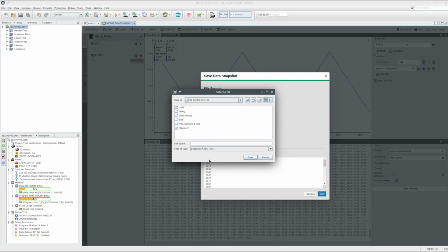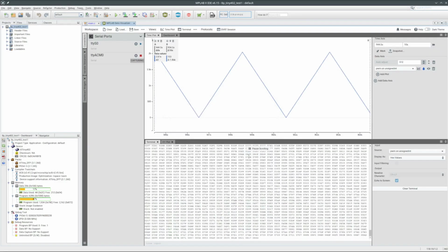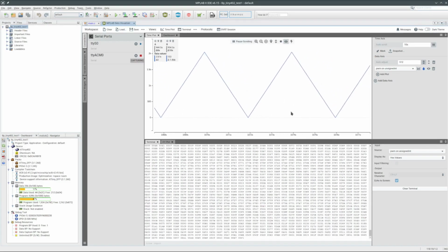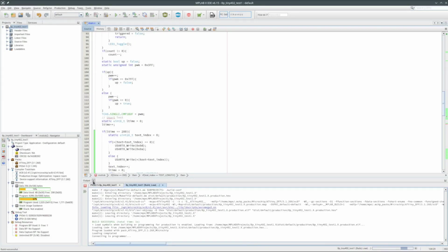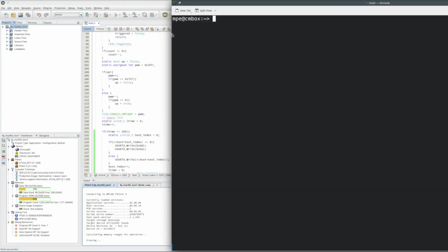I could see the graph coming in very handy if looking for a variable that is way out of range, or values bouncing around when they shouldn't. Yeah, that's better than anything I've written to view my microcontroller data. Very nice. Sometimes outputting data in ASCII format is going to be preferred. Other times the raw data will work out best. The MPLAB X Data Visualizer seems to do a pretty good job at viewing either format.